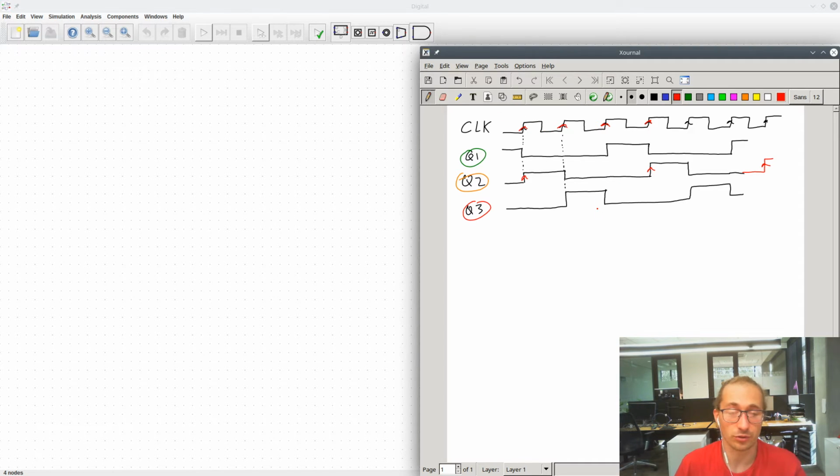So there's 2 approaches we could use to this. We could use a ring counter, or we could use a binary counter with a decoder. We'll cover both options, and then it's really up to you which you prefer. So the binary counter option has 3 states here, and to record 3 states, well, I need at least 2 bits, because 1 bit can only keep track of being in one of 2 states.